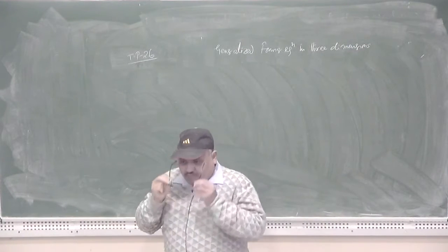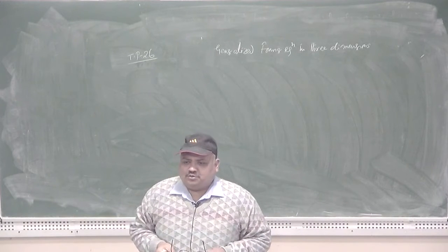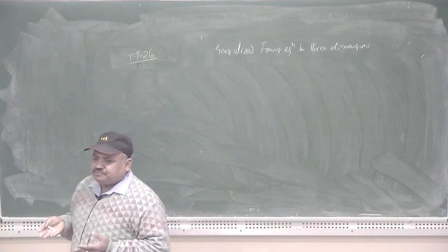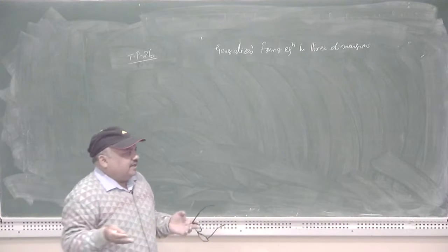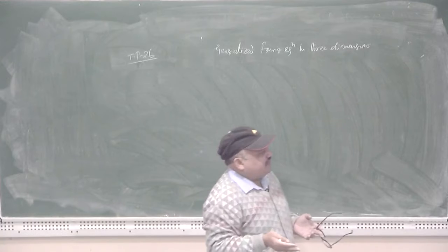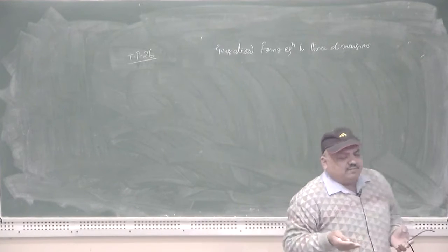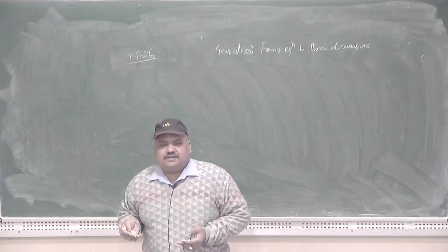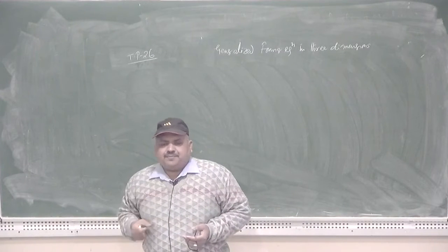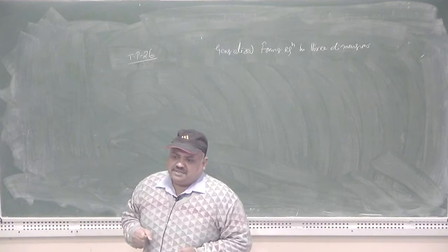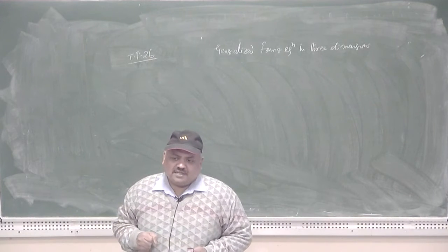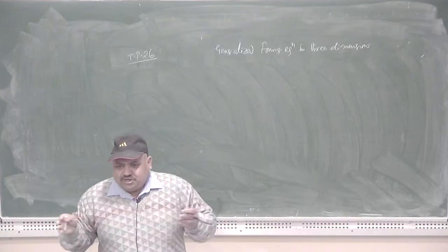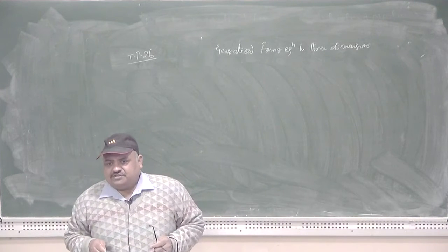Then we must talk with respect to the 3 perpendicular Cartesian coordinate system, or the spherical polar coordinate system, that is r, theta, phi, or the 3 coordinates as appear in the case of the cylindrical polar coordinate, that is r, theta, z. So, in the present class we will see the extension of equation number 1, that is q by A equal to minus k del T by del x, to the 3-dimensional Cartesian coordinate system.